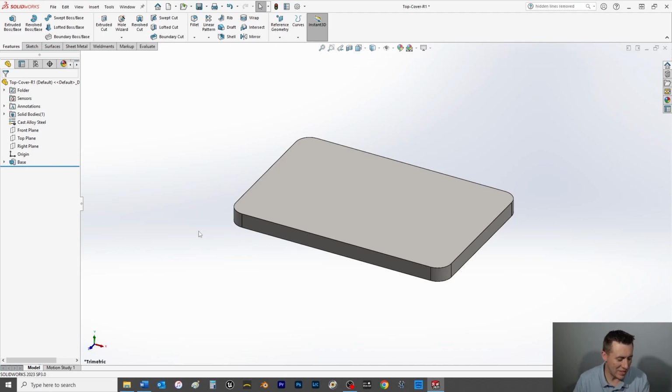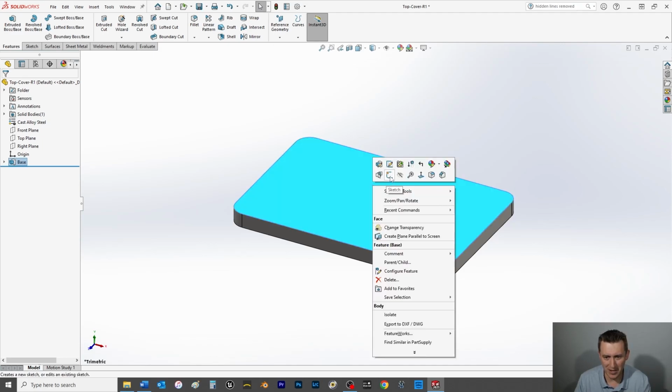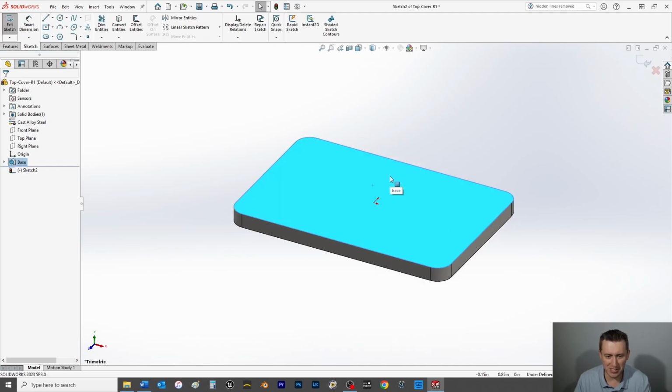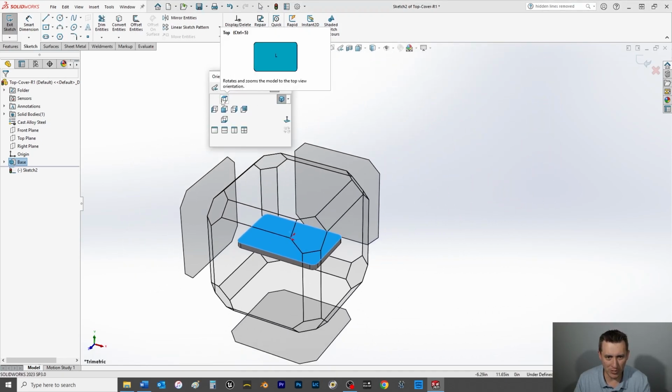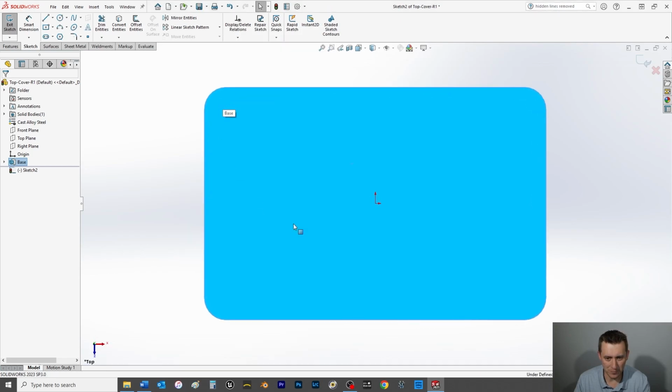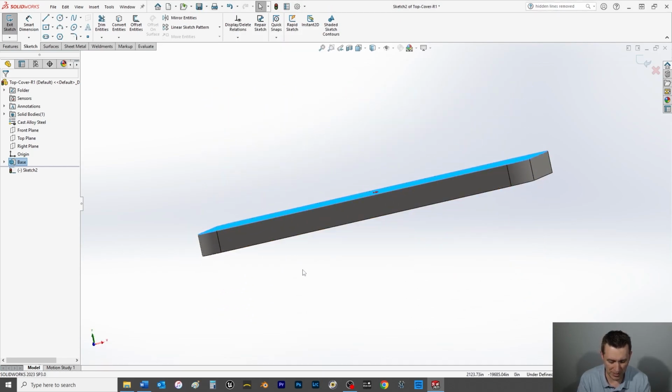So, now moving on to section 4.5 on page 137, we will simply right click on this top face here and we will choose a sketch this method. Then we can hit the space bar and we can do one of two things. You can do the top view, or you can just simply Control 8.